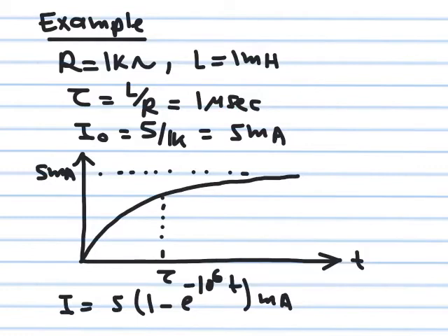And the steady state current, or the peak current of the inductor, is 5 over R. So 5 over 1k, so it's going to be 5 milliamps. So this is how the inductor current changes with time. It starts with 0 and gradually and slowly, using this expression that we derived, is going to build up to 5 milliamps at infinity. Tau determines how fast this current grows.